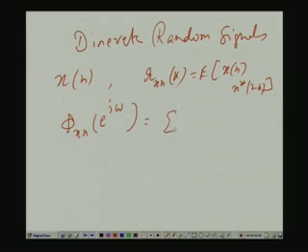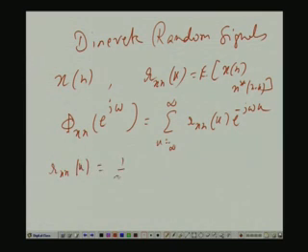After all, what is DTFT? This is the formula given R x x k. If you take its DTFT, it is this. So, it is actually a power series in e to the power j omega, k from minus infinity to infinity. Okay. Then what is R x x k? It is the inverse DTFT. Similar treatment, you see, minus pi to pi.